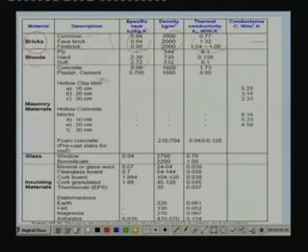When it comes to hollow clay tiles or hollow concrete blocks, the thermal conductivity values are not given because here the heat transfer, as I have discussed just now, is by multimode: convection, conduction and radiation. So for these materials, the conductance values are given. These values are generally obtained from experimental measurements. For example, for hollow concrete block of 10 centimeter thickness, this is the conductance value. For 20 centimeter thick, this is the conductance value. For 30 centimeter, that is the conductance value. Similarly for foam concrete, this is the density value and this is the thermal conductivity value. Similarly for glass and for insulating material.